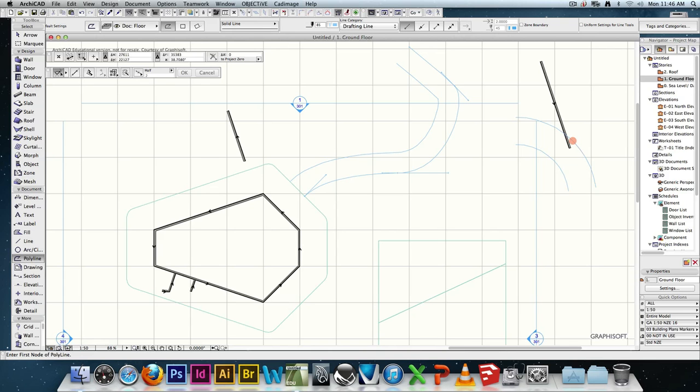Okay, and then you can type in D1500 if you want to, and it will... Oh, no, hang on. You've actually turned yours off somehow. It's actually that thing there. You can go out and click any of those things, even though you're in the middle of drawing. To the right of that? Yeah, see, now it's popped up again. So you go D, see, that pops up there. It was actually popping up before, but it was popping up in there. Yeah, and just hit return. And that is 1.5 meters wide, which is the width of the path. Exactly. And so you can do exactly what you just did then, but do it to the spline.